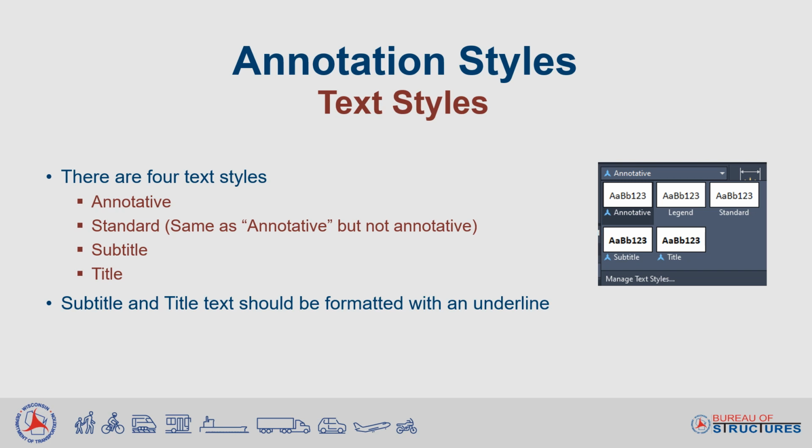There are 4 text styles in the Structures template. Annotative, Standard, which is the same as annotative, but it's not annotative, Subtitle, and Title. Typically, the subtitle and title text styles should be formatted with an underline.